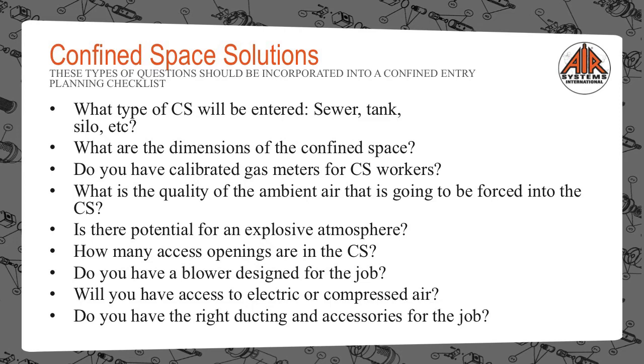What is the quality of the ambient air going to be forced into the confined space? Is there potential for an explosive atmosphere? How many access openings are in the confined space? Do you have a blower designed for the job? Will you have access to electrical service or compressed air? Do you have the right ducting and accessories for the job?